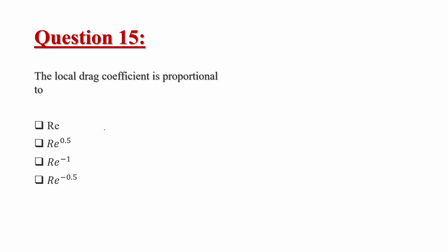So what will happen? Suppose we have an eddy that is created here. That means some disturbance is created here and it was having some u max, that means some maximum velocity. So what will this eddy try to do? Say this layer has a velocity that will be less than this layer, because this is the maximum layer and here we have the zero velocity. So this velocity will be somewhat less than this u max.